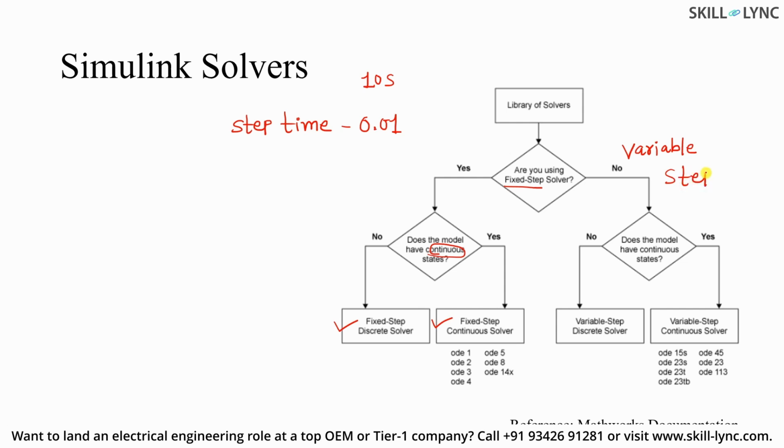Now who is going to change the step time? MATLAB itself, in the backend, is going to take care of the step time. So the step time is not fixed; it's going to vary according to your configurations and the way MATLAB treats the model. Here also you have another two categories, which are variable step discrete solver and variable step continuous solver. And here you have fixed step continuous solvers and variable step continuous solvers.